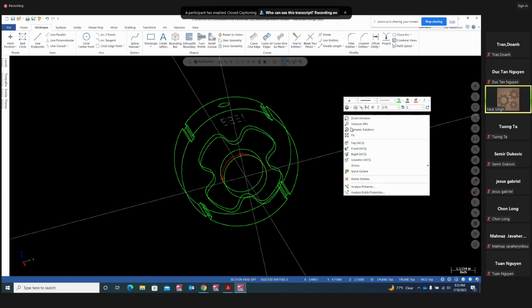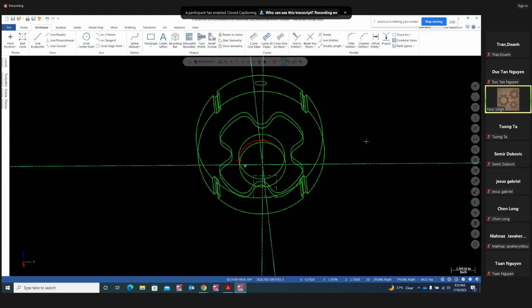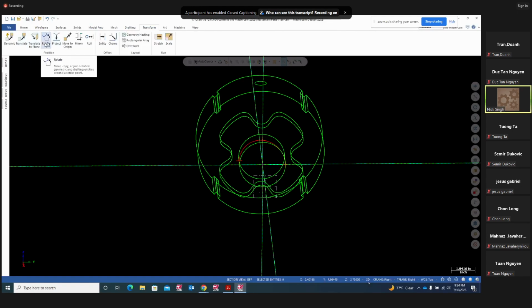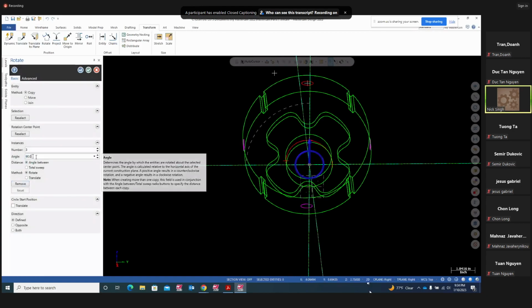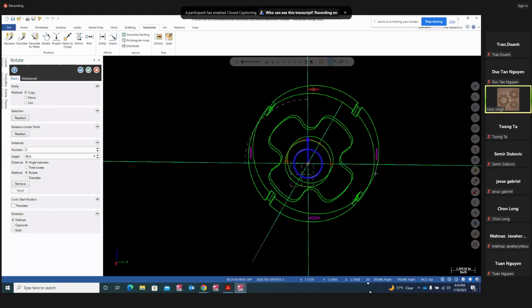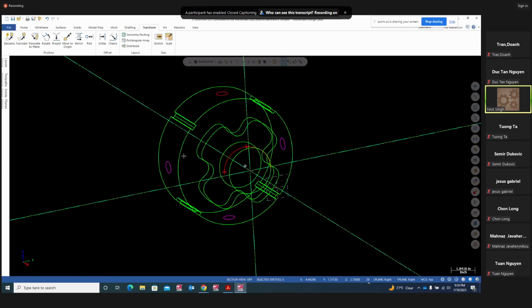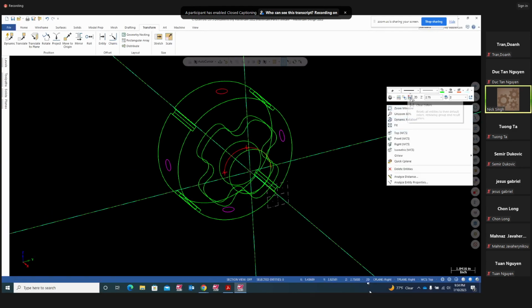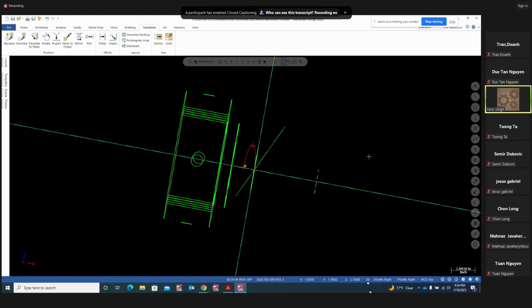Now I can rotate that. How can we rotate that? Go to construction plane right. Make sure you're in construction plane right. I'll go to 2D just in case. I'm going to go to transform. I'm going to rotate this guy. End of the selection. Rotation angle is already 90 degrees. And we want 3 of those. So we got 1 here, 2 here, and 3 here. We got those holes. Right click, clear colors. So that finishes your geometry, guys.